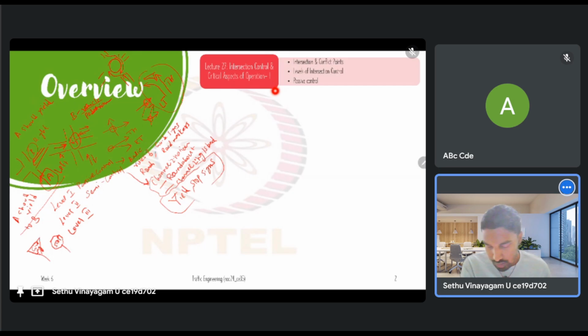So stopping is not necessary in the case of yield; only if required do vehicles have to come to a complete stop. But if there is a stop sign, it means that whether or not there is a safe gap available, the vehicles must come to a complete stop, then look at the conditions, and then proceed.